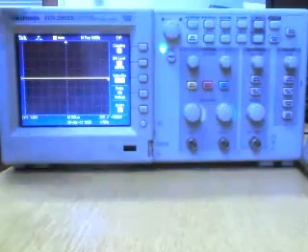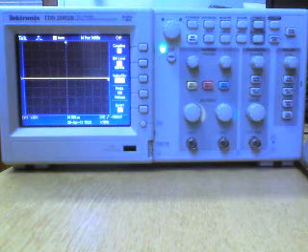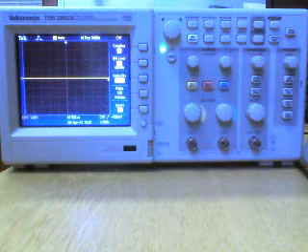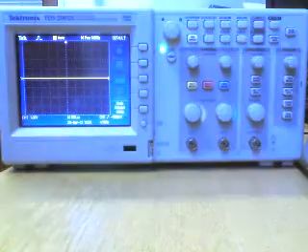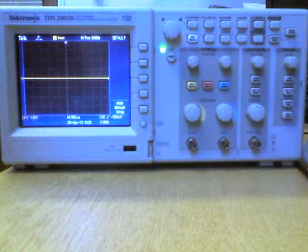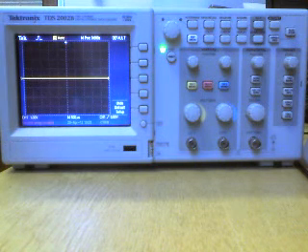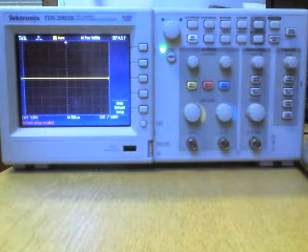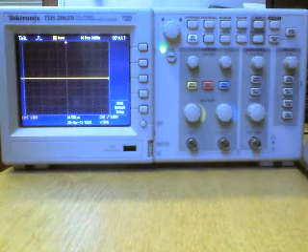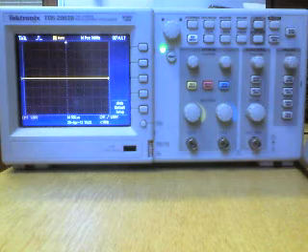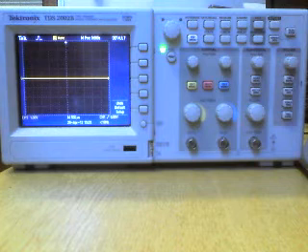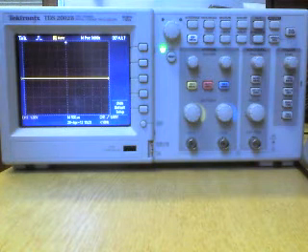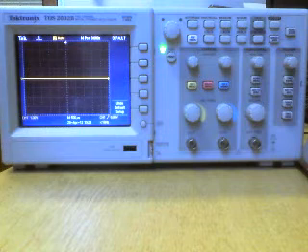Now then, whenever you switch the oscilloscope on and it's all powered up, the first button to press is default setup. Okay, hit that button, it will go back to its factory settings. So if anyone's messed about with their time base, volts per division, triggering, whether they've used any measure functions, cursors, whether they've changed the way the oscilloscope acquires the images or displays the images, and so forth. Okay, if anyone's messed about with any of those, it can make life a hell of a lot harder trying to reset up the oscilloscope.